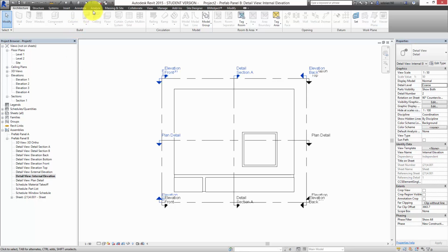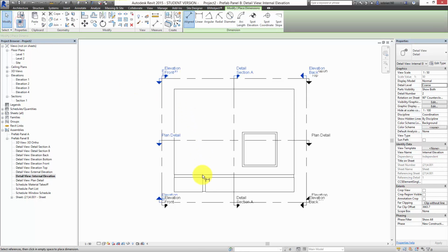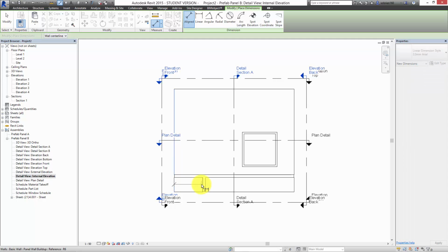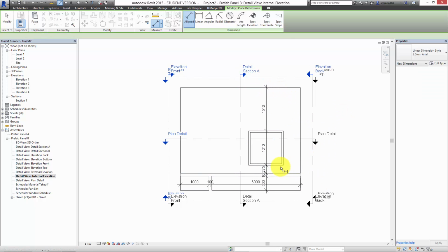This is where you start to actually annotate and make some detailed dimensioning as a component drawing, dependent on the method of procurement you're talking about, as to whether it's going to be made completely in one factory or farmed out in different factories. It depends on how you set up these component drawings. But what you should really do as well is give an overall dimension like this, but you should also give a dimension to the tolerances on the edge,